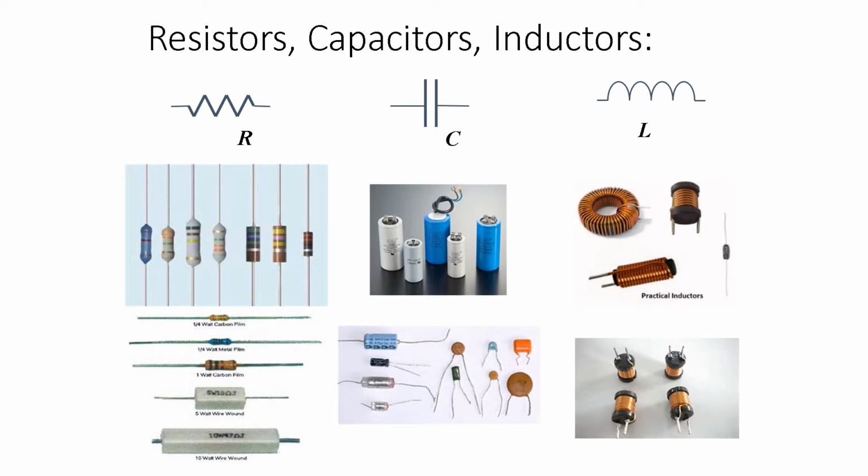If you go significantly beyond that, you can essentially burn out your resistor very quickly and leave a black little smoky mess behind. So different types of materials are going to allow you to do different wattages, and there's a couple other things that are going on behind the scenes there too, but I just want you to know that with resistors, you want to size the correct wattage for what you're doing in electrical, otherwise you can have problems there. So resistors are pretty much the most self-explanatory.